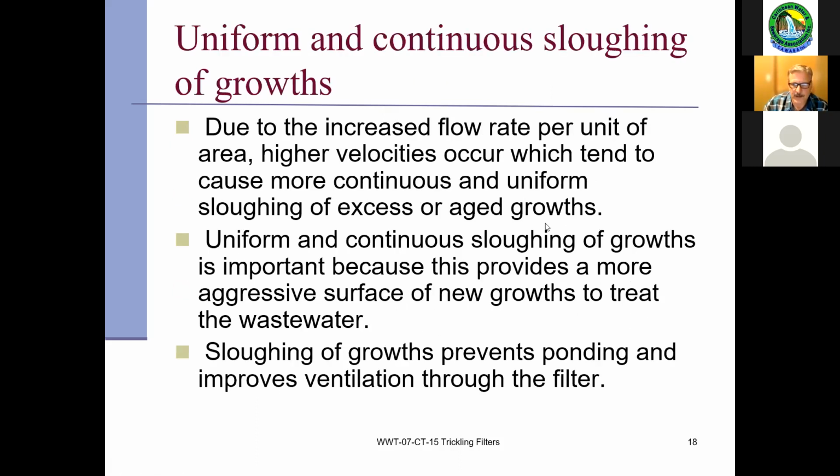With any of these fixed growth systems, there's going to be continual sloughing of that biomass. As it gets a little older, it's basically getting heavier, and it's going to slough off a bit, and you need to be able to remove that. And it's important that that happens so you have new growth continually happening all the way along.